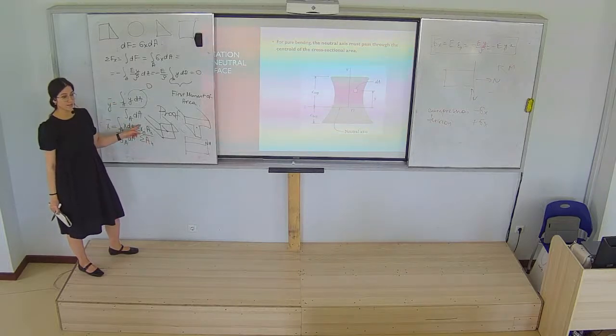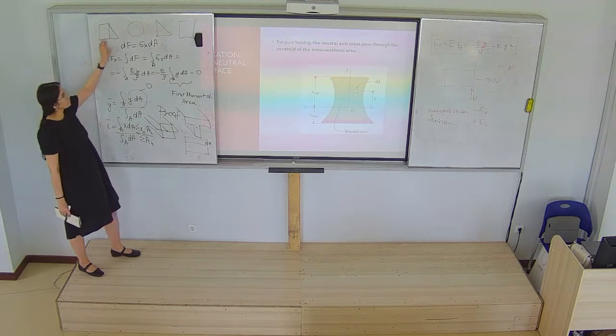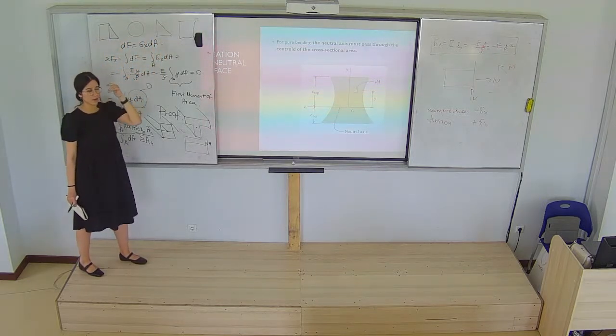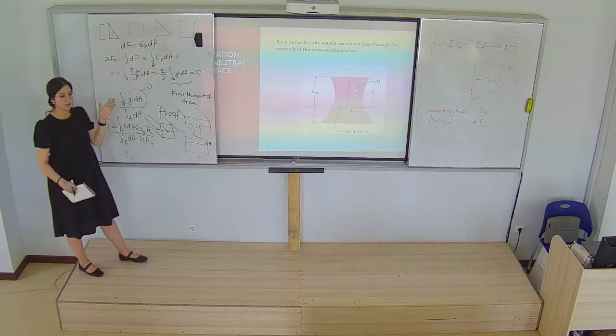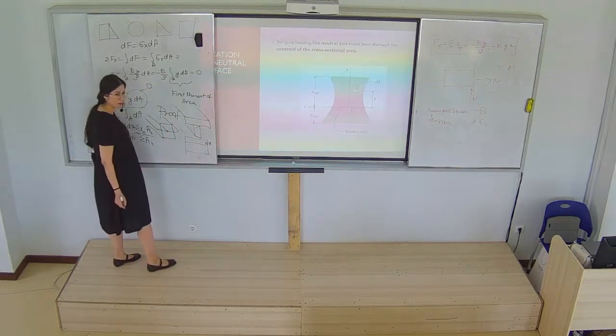How to find the center of mass. It means that we will have complex shapes. By using complex shapes, it will not be just a circle, it will not be just a triangle or rectangle. It will be a bit complex. For example, I shape, L shape, T shape beams. How will we find it? We will divide into two parts. If it is a T shape, we will divide into two parts.